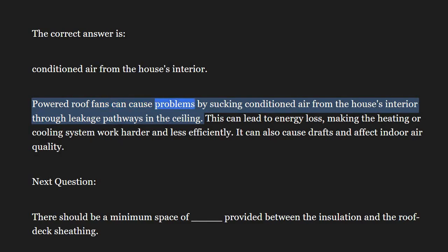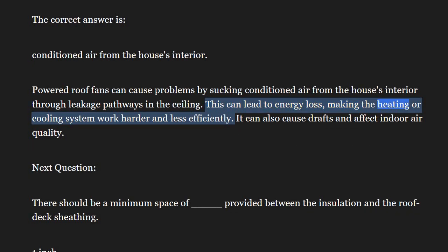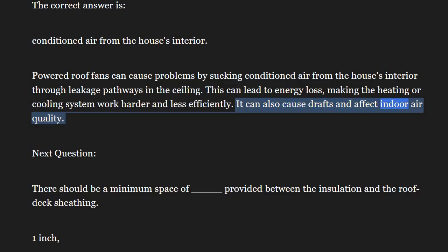Powered roof fans can cause problems by sucking conditioned air from the house's interior through leakage pathways in the ceiling. This can lead to energy loss, making the heating or cooling system work harder and less efficiently. It can also cause drafts and affect indoor air quality.